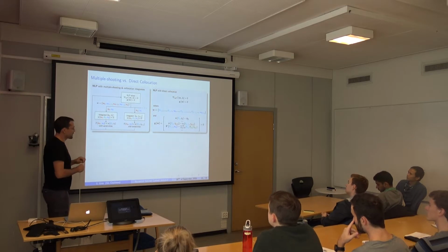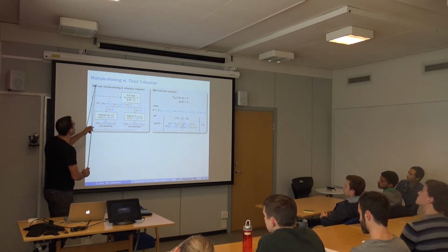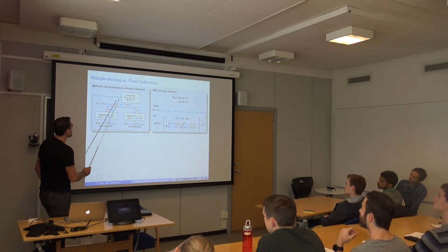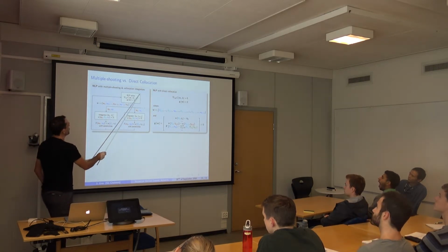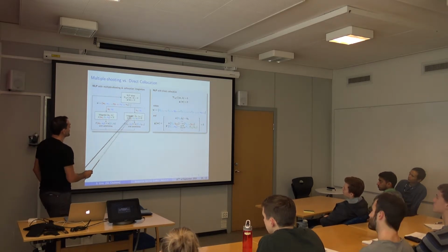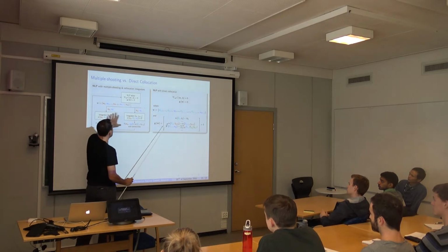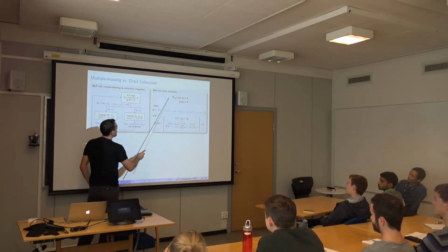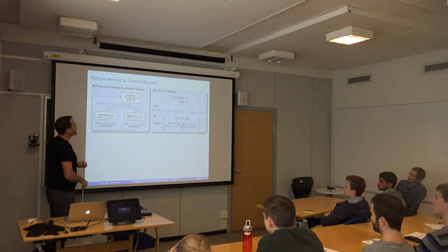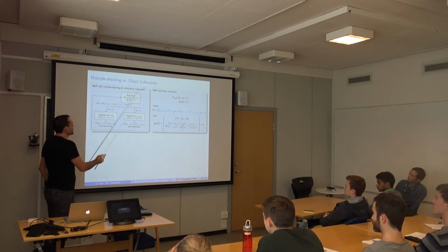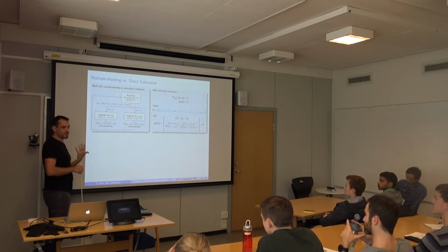Okay, now just as a passing comment, I will not dive too far into this, but just to show you this thing. We started from here actually to explain direct collocation, and essentially that's if you would deploy collocation-based integrators inside multiple shooting, and we had this picture where you have Newton schemes operating at the level of the NLP solver and then inside the integrators. And that's one way of doing it. And if you move to direct collocation, you bring everything into the solver. So now the NLP problem has this form with the KKT conditions with all the constraints together in G. But at the end of the day, if you look at all the constraints you have to solve in direct collocation, or all the constraints you're solving in multiple shooting plus collocation-based integrators, you're talking about the same constraints. That's the same equations that you're solving.